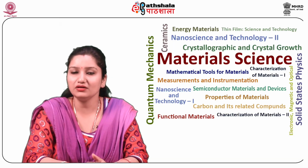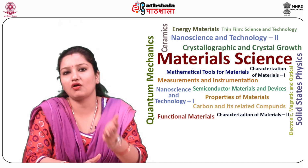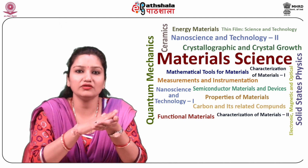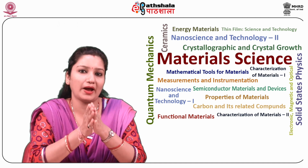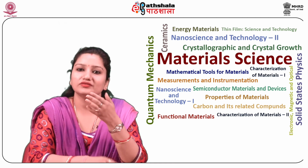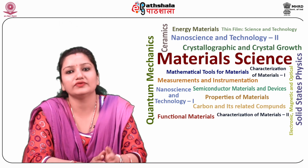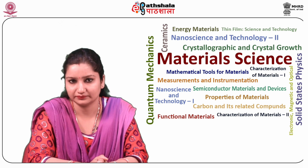The next step is the liftoff process. There are some materials which are not easy to be etched. In those cases, we pattern the photoresist on the wafer where we don't need the pattern of desired material, such that it leaves the desired places uncoated with the photoresist using a dark field mask.